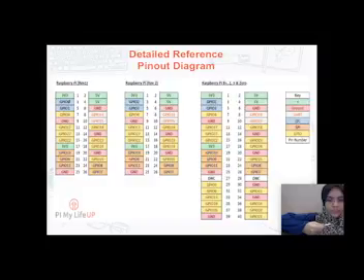As we can see, it is not only focused on the standard pins but also a reference for I2C, SPI, and UART. The I2C is the inter-integrated circuit pins that connect and communicate with hardware modules supporting this protocol, which usually uses around 2 pins, and the SPI is the serial peripheral interface, somewhat like I2C but with a different protocol, while the UART is the universal asynchronous receiver transmitter serial pins that communicate with other devices.